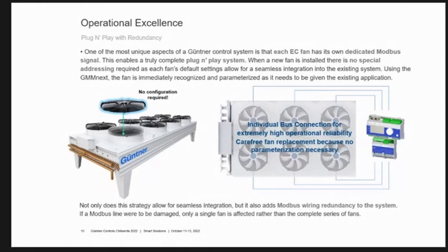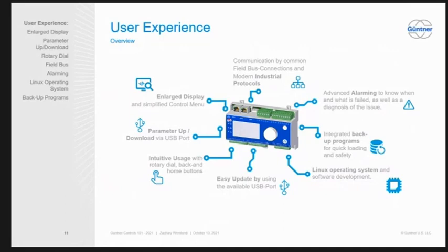But that's a blowout of our actual GMM controller. You can see we have a rotary push dial, so it spins and pushes. The user interface on our new GMM is a lot nicer compared to our previous generation. This is the USB port where you can upload and download configurations and upload the software. We have built-in Modbus TCP and RTU in the controller.